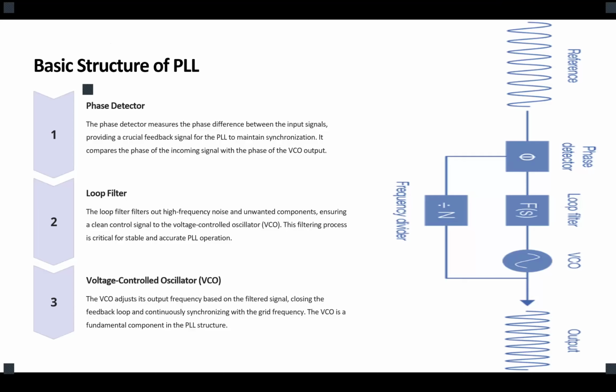If you have a solid sinusoidal generator, your frequency is constant. It won't change. But you want it to change if the grid changes frequency. So you need a dynamic system where the VCO, in real time, changes the frequency of that sinusoidal based on the measurements.